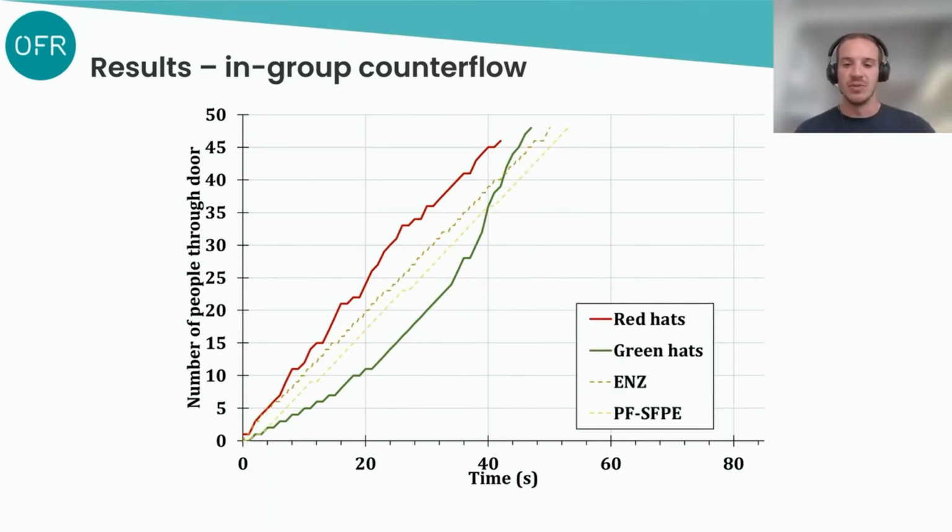Again, we'll compare the results firstly to the evacuations and the SFP modes in Pathfinder, which show comparable results themselves, and then also comparable to the trial results, albeit marginally conservative, with the flows being slightly slower overall. While agent interaction, or the in-group identity dynamic, could be implicitly represented within the computer models, for example, by altering some relevant parameters, we decided not to incorporate this due to a lack of data to support any changes in the value of these parameters, and rather just kept the same simulation as was.